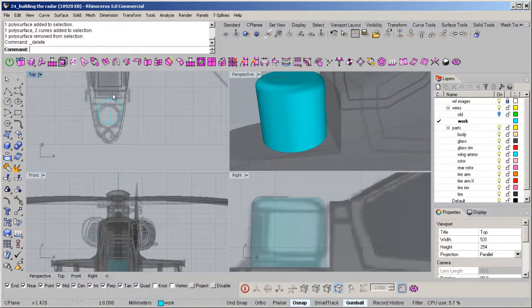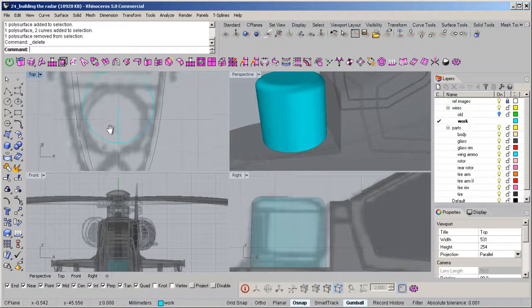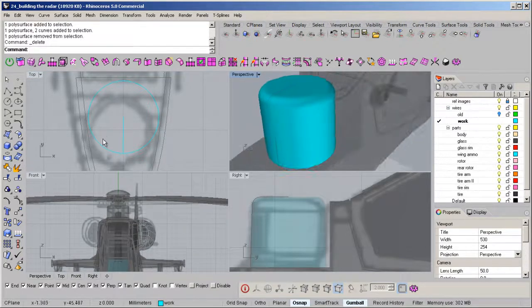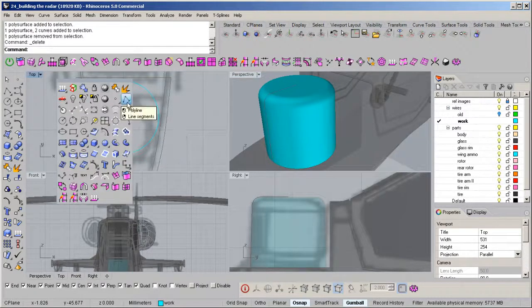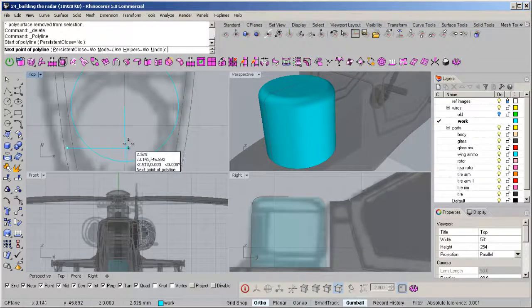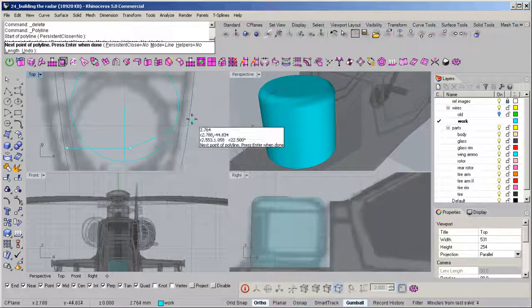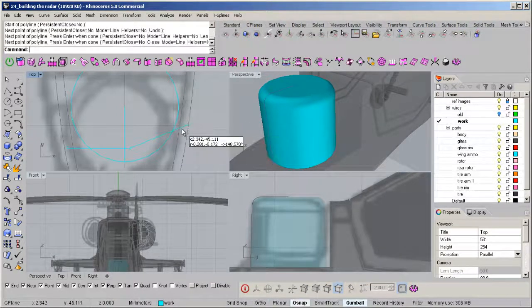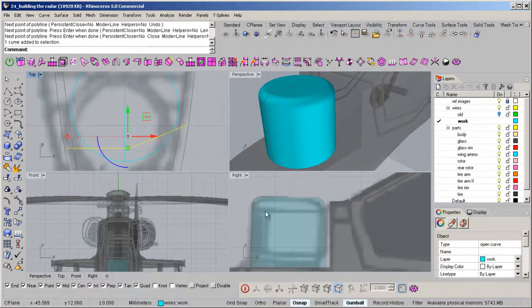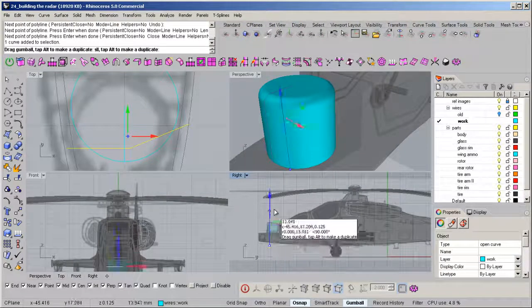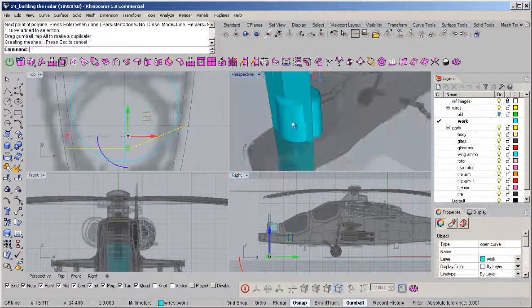Switch over to the top view. The front part's a little bit flat for the lenses, so we need to create a poly curve. I'm going to guesstimate it is somewhat like this, and it goes out something like that. When you use a gumball, translate and pull it up, hold the control key so you can create a surface.